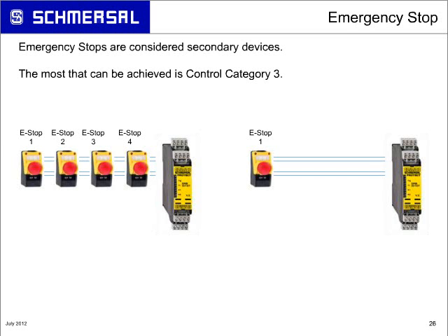It's not designed to be used as a normal start-stop button to be actuated every 5 minutes. It's there for emergency purposes. You probably test the E-stop, or should be testing the E-stop, more often than what it's really required. Hopefully you never need an E-stop, but in the cases that you do, it's there, so it's a rare occasion that you need to even call the demand for the E-stop.